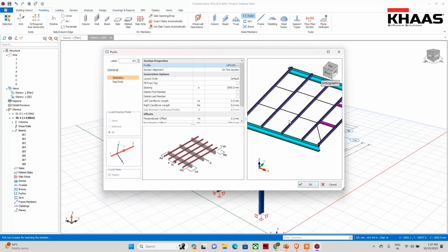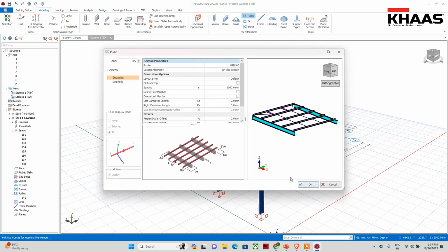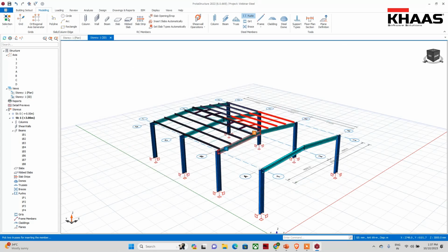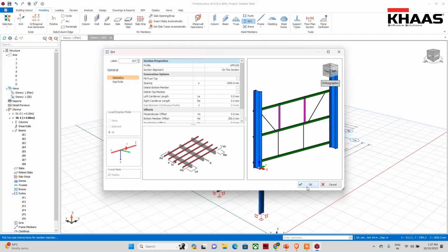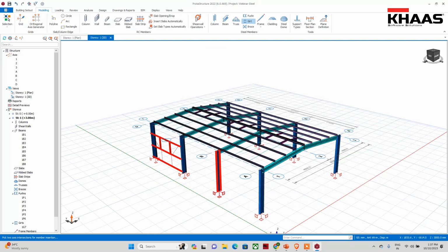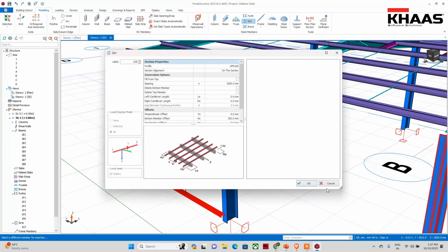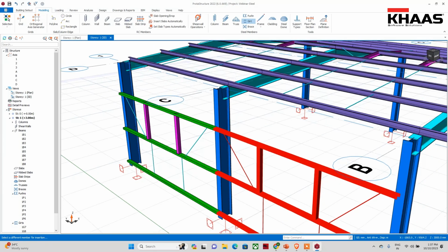With the sag rod there, suppose you wanted to remove the sag rod, you can do it. So then 1, 2, okay, same thing you can apply to your geometry creations. You can also do it manually by selecting the axis point using the column and beam options, and the frame options you can use for slanting or any slope related way. So for the wall grids, the same you can do. So here the on section is there, suppose I hit OK, yeah, it's okay. If the members are not placing properly inside, you can also change this from on the section to under the section. So for me it is working fine.